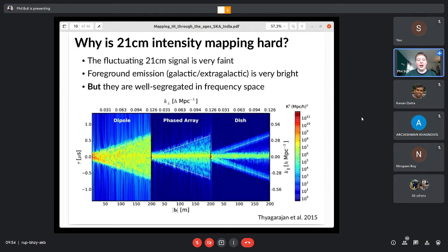And what happens is that modulation essentially scatters some of that nice smooth structure, which would be at very low Fourier modes. In this case, we've taken a Fourier transform along the frequency axis. We'll call that delay, tau, for reasons I'm not going to go into if you're not already familiar with that. So tau of 0 means nice, perfectly smooth. That's a 0 or DC mode in your Fourier transform. And as you move away from tau of 0, you're looking at shorter wavelength fluctuations in the frequency direction.